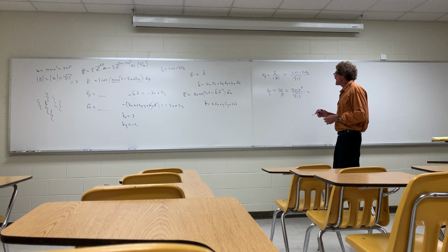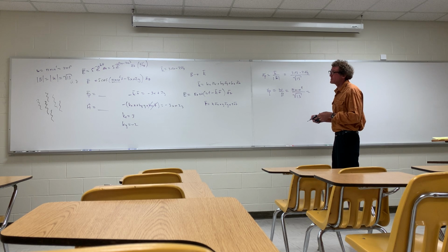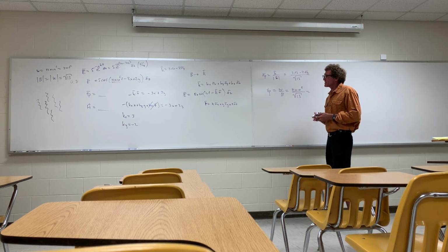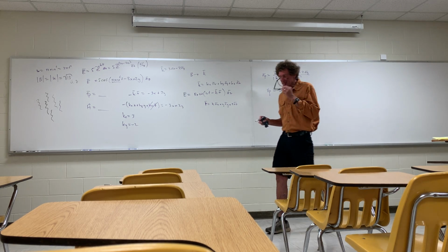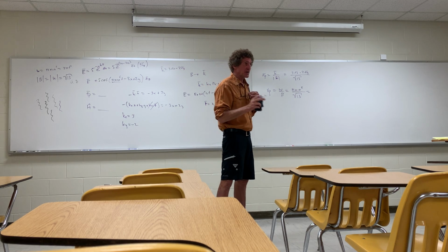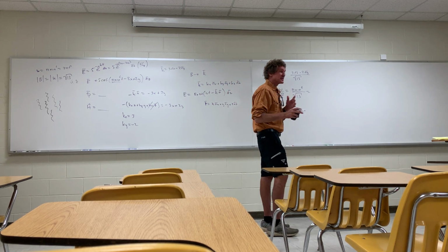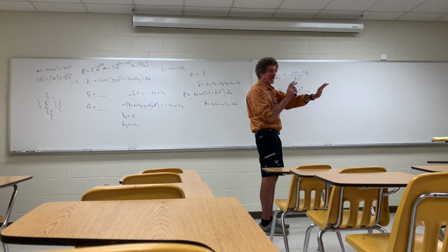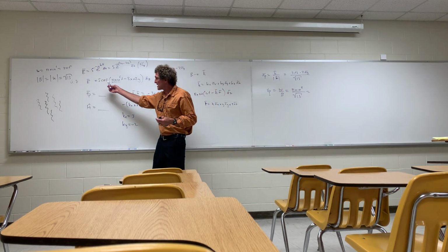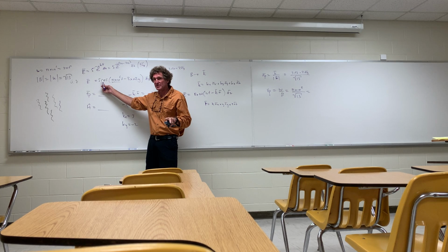Now this phase velocity is quite a bit less, and I think this is where Whitworth made a problem, because what we need to get is the intrinsic impedance of the media. Do y'all follow me on this, class? We have to get that. The way we're gonna get that is, I'm gonna tell you, he should have put down it's non-magnetic, and I can see it's lossless, because there is no e to the minus alpha z here, so I know it's lossless.